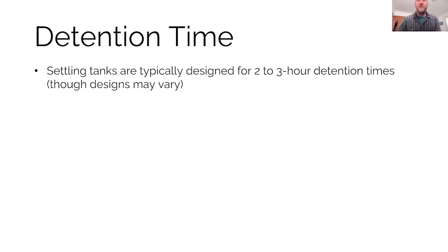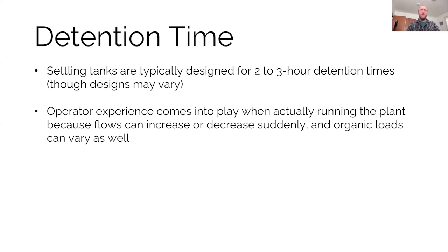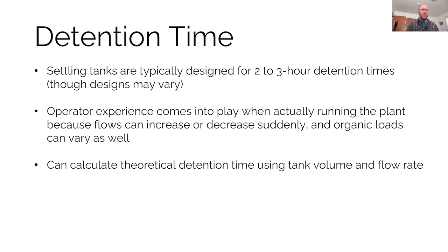Okay, so briefly, I'm going to talk about detention time. This is important, of course, because particles take a while to settle out. Depending on how long they're in any given vessel, different sizes of particles are going to have time to settle out. Typically, these settling tanks are designed for 2 to 3 hour detention times, although, of course, different systems might vary. And your experience can come into play when flows suddenly increase or decrease, where maybe you need to adjust some different processes to help the settling.